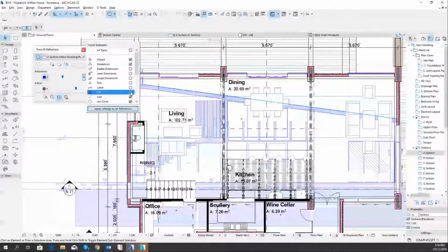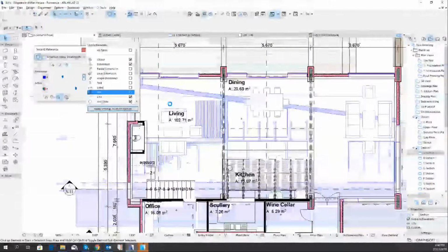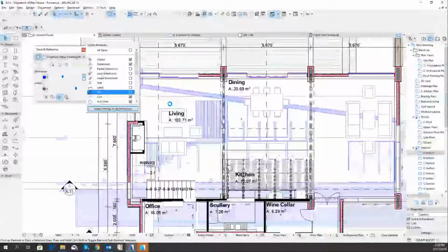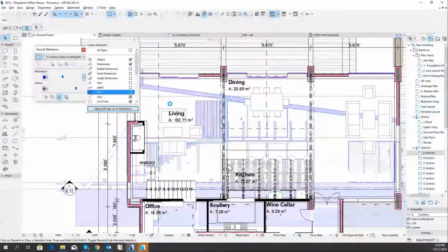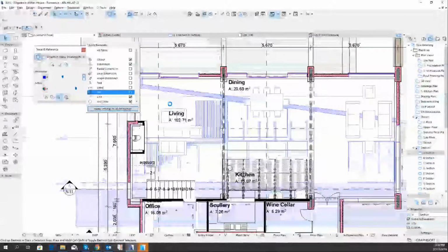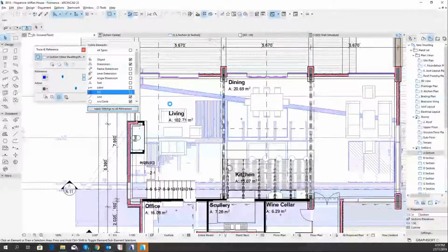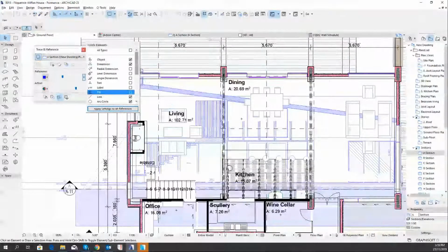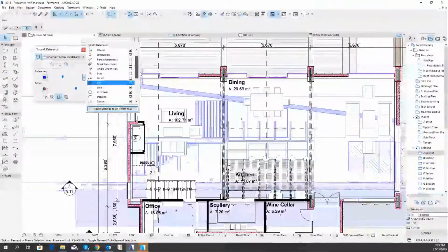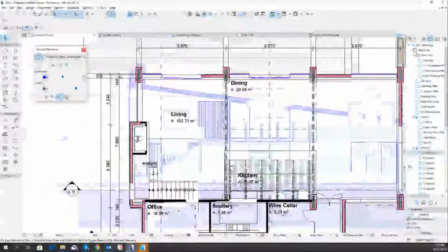Actually, I'll try and hide fills just to see if it does something. So that's quite useful when you have a drawing which has got a lot of information on it and you're bringing it through as the trace reference, but you only want to look at certain things, maybe just the walls or some line work, something like that. Was it not done? Maybe it wasn't a fill. Hold on.